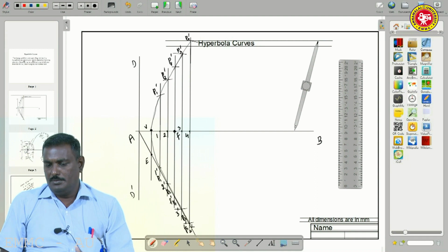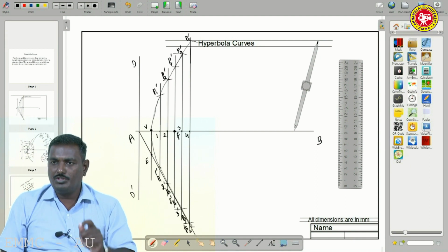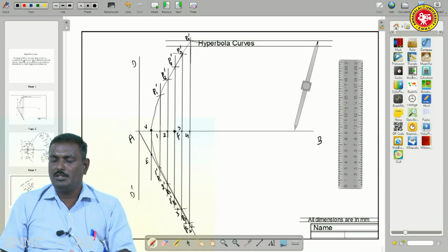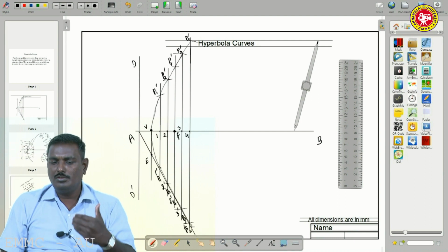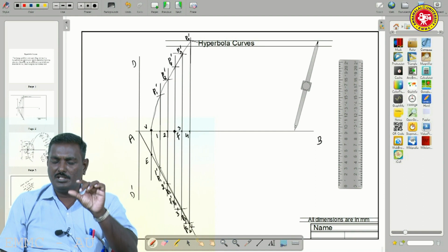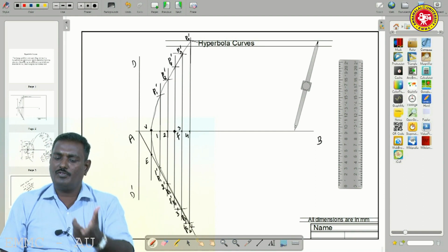So up to this we have completed by use of the 2H pencil. By use of the 2H pencil, please construct all. Already I said, while you go for any construction, initially use the 2H pencil. Then only, after you get a proper curve, you go for tracing.